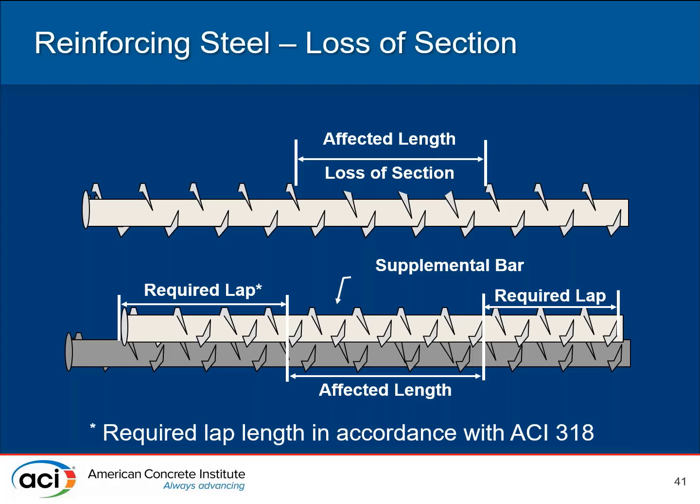And there are situations where you've done the demo, you've exposed all of the corroded steel, but particularly if you're losing a lot towards one side of your opening, the lap required may need to extend into additional concrete removal, extending into the otherwise good areas. So